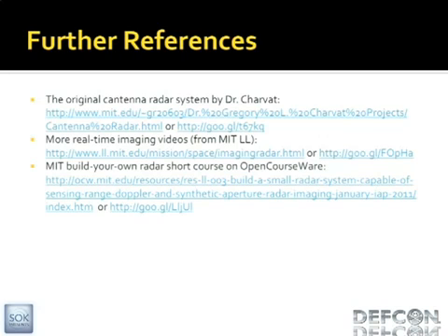Is the upper frequency limit defined by how easily you can obtain a reference signal? The frequency bands that you can operate in, there's a few bands. You pretty much are stuck to the ISM bands if you want to do this legitimately, because those are licensed for this unrestricted or pseudo-unrestricted use. So you could go up to 5 gigahertz.